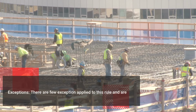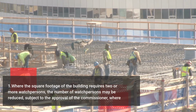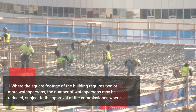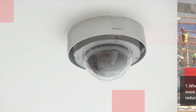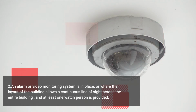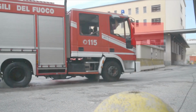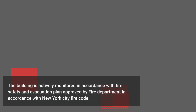Exceptions. There are a few exceptions applied to this rule. 1. Where the square footage of the building requires 2 or more watchpersons, the number of watchpersons may be reduced, subject to the approval of the commissioner, where 2. An alarm or video monitoring system is in place, or where the layout of the building allows a continuous line of sight across the entire building, and at least one watchperson is provided. The building is actively monitored in accordance with a fire safety and evacuation plan approved by the Fire Department in accordance with the New York City Fire Code.